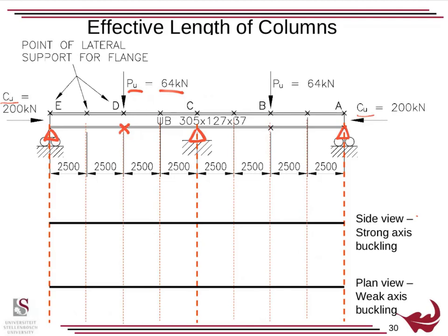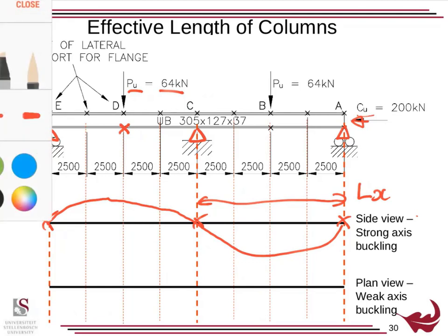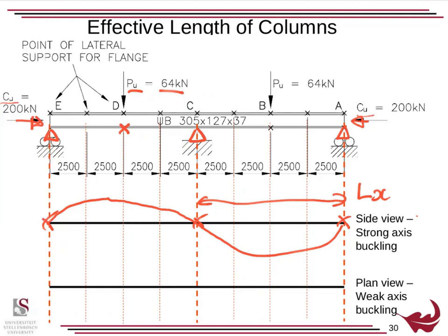But coming back to buckling, if we walked up into the structure on site, we load it and load it and load it, eventually it gets to the edge, I'm going to fail now, and it can't move upward there, there, or there, and it would look like this. If we looked at it from the side, it would look like that. So our effective length, Lx, is this length there. It would physically look like this on site. It can rotate at these positions, so our effective length would be Kx is 1, because it's pinned in all these positions.